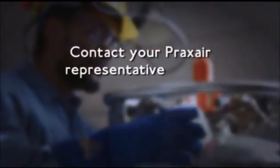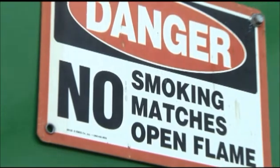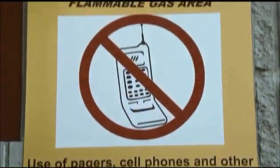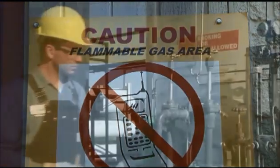Contact your Praxair representative before attempting any cleaning for oxygen service. And always keep sources of ignition away from oxygen storage and work areas. Post appropriate warning signs at strategic locations.